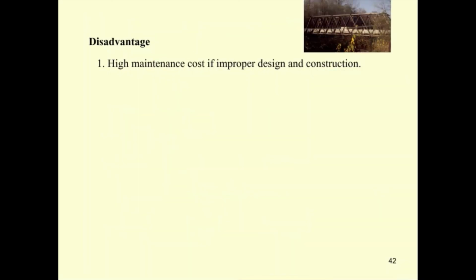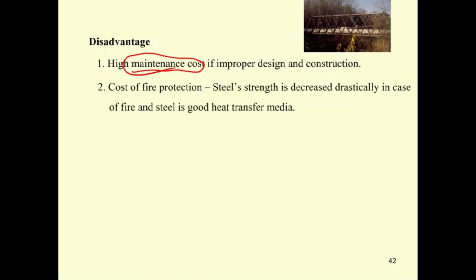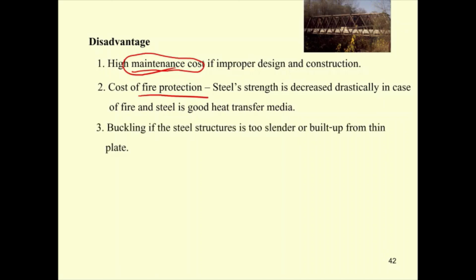Disadvantage: high maintenance, which we talked about before, because of both fire and rust. You have to put on fire protection, which is going to reduce the heat transferred into the steel. And buckling is a problem.